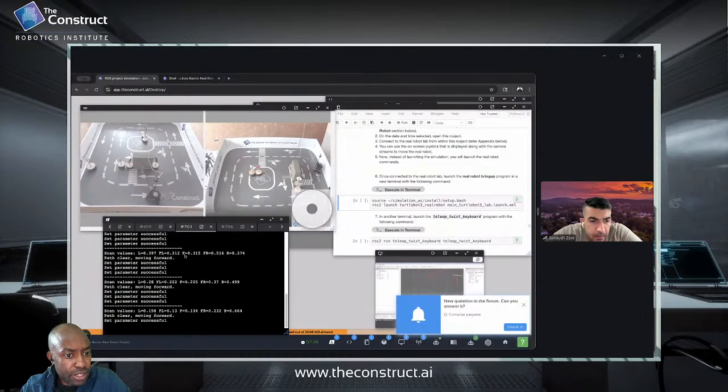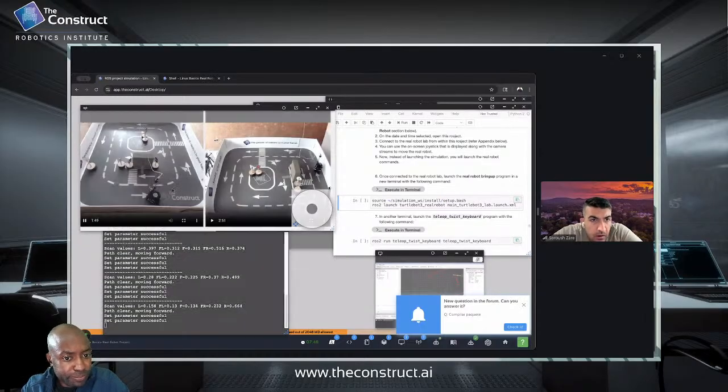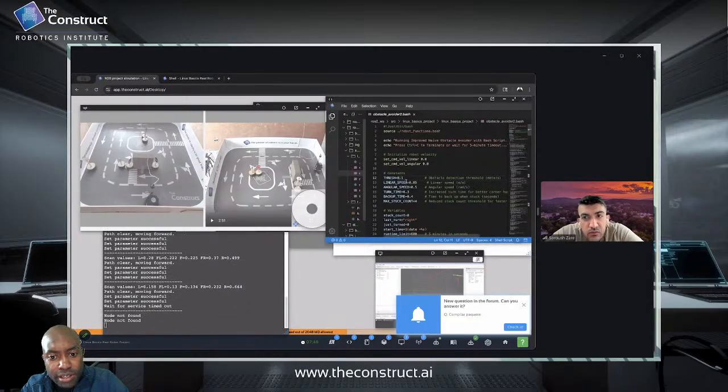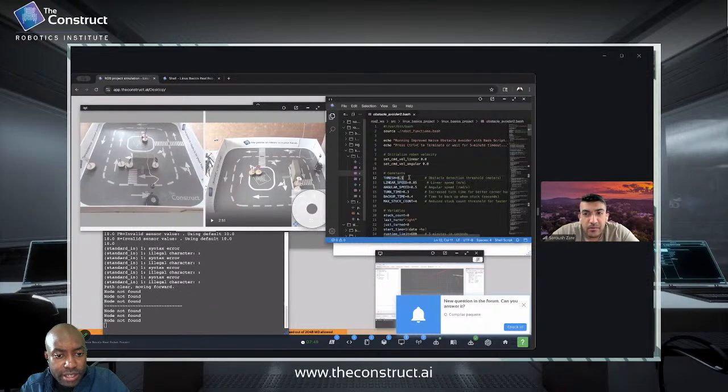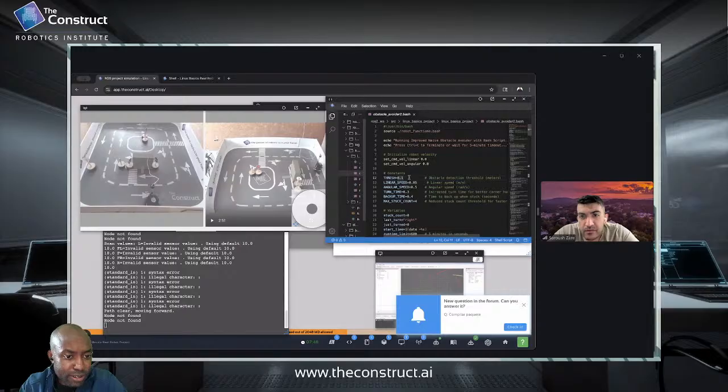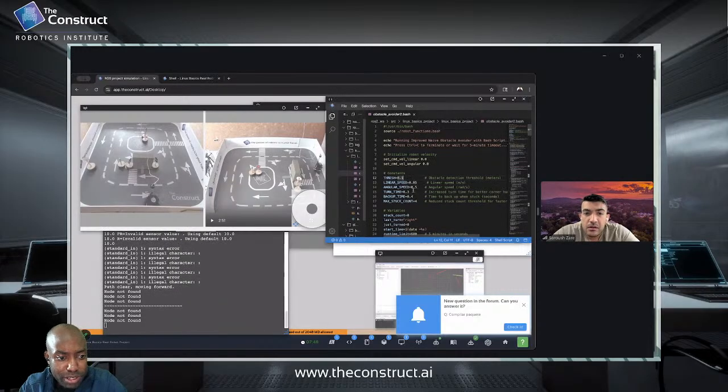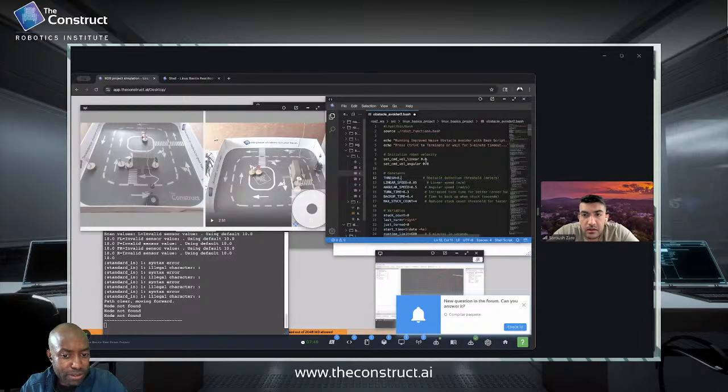You're still using a threshold of 0.3, is that right? No, 0.1. 0.2, 0.1. Yes. Okay, why? In simulation, it works with 0.1. Well, there's a difference: in simulation 0.1 might work, but on the real robot it's hardly 0.1. So did you try using 0.3? What happened when you used 0.3?